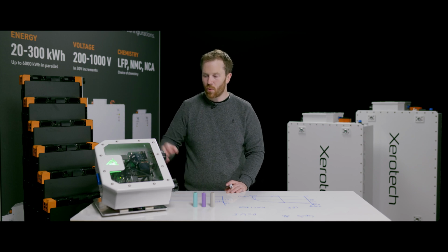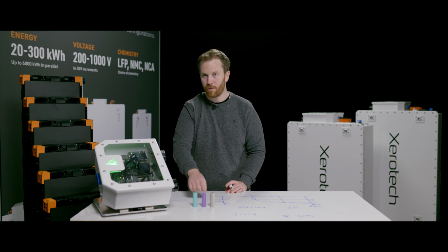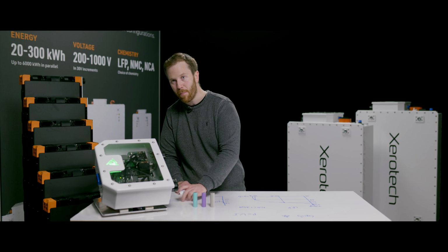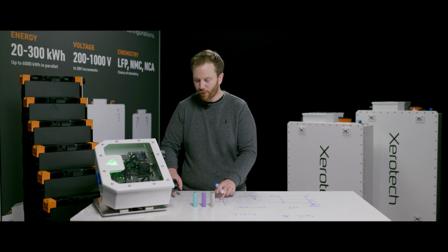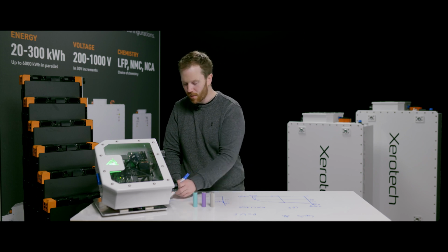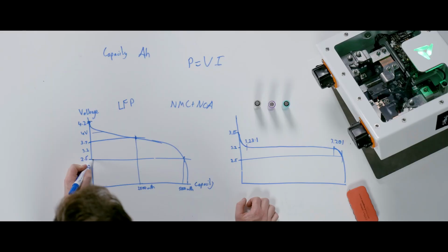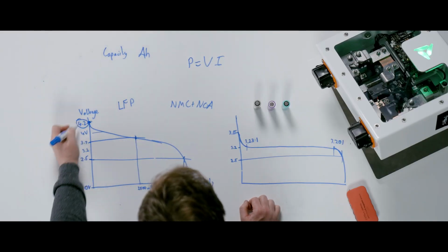But that's still a very small voltage difference, so you need very high precision measurement to understand the difference between the two. So in our battery management systems, we use a different method for calculating the state of charge, or a combination of a few. We're actually counting the amount of amps that flow at any one time. It's called Coulomb counting. And then we'll switch back to voltage estimation in different parts of that curve. The other important thing to understand with lithium-ion batteries is these limits of voltage.